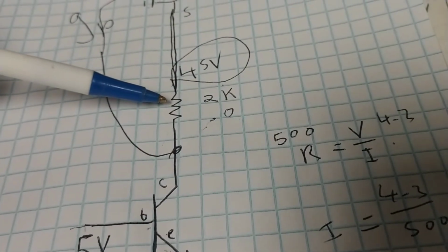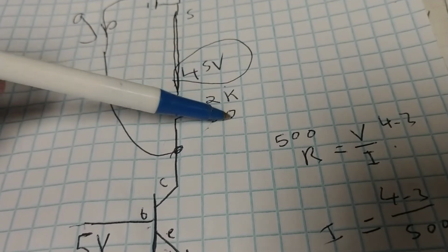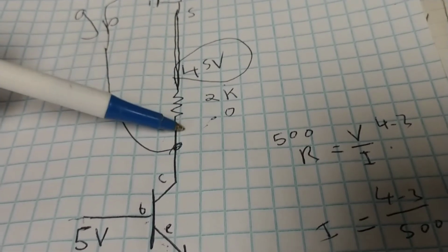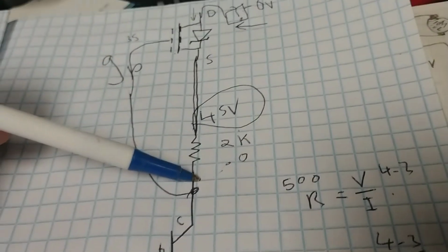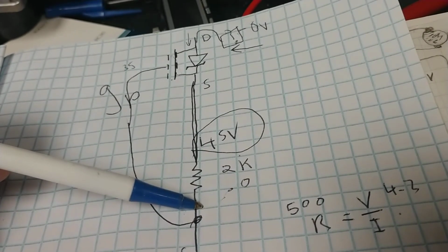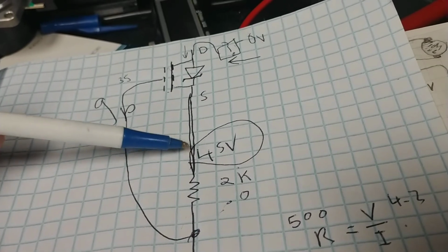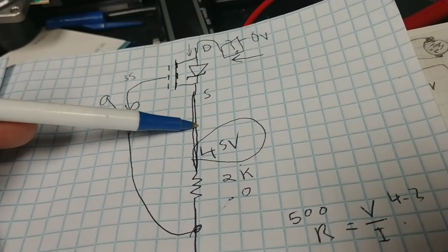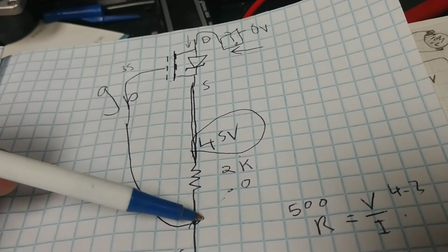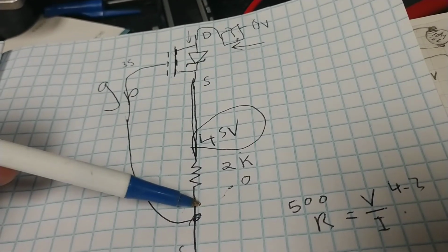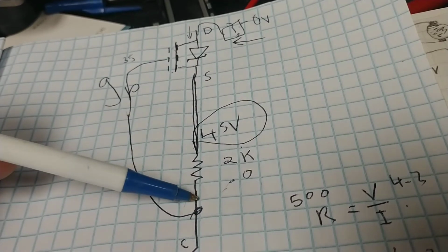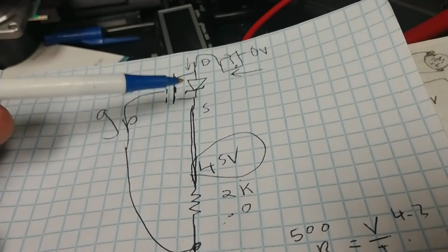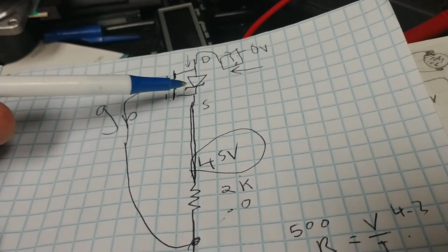So when I did the calculation, knowing its resistance and knowing the current flow through there, you can then calculate the voltage, and it came out to something like 25 volts, or 20 volts. So 20 volts down from a 45 volt side would bring that to 25 volts. And that's just close to the limit of what the spec sheet says this p-type power MOSFET can handle.